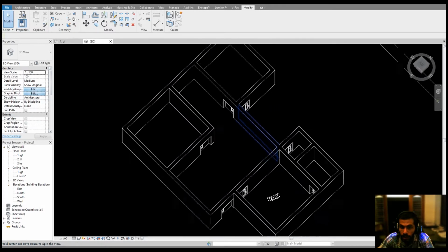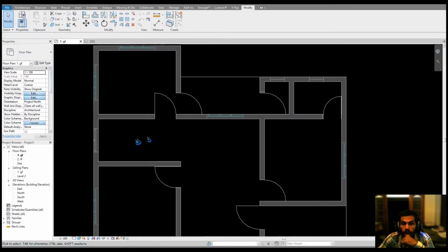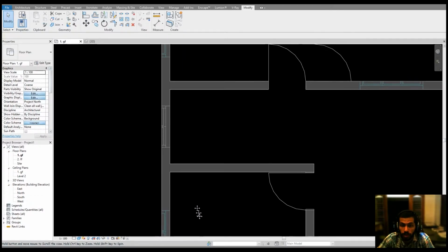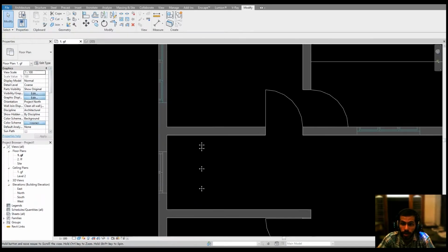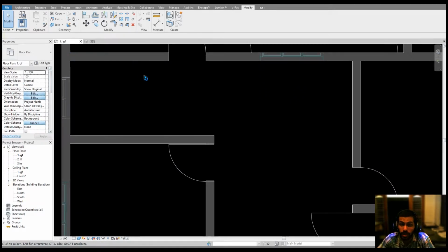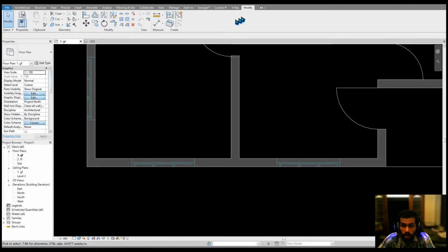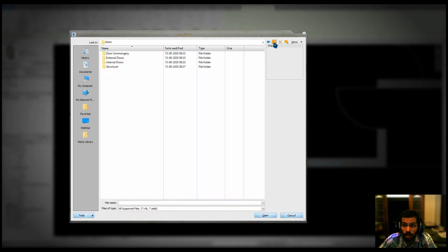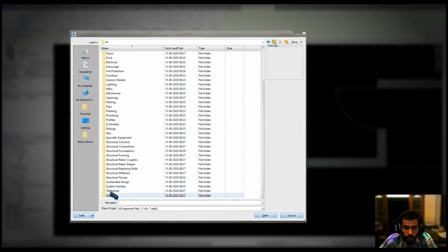Alright, now let's try placing the windows here. There are a couple of 3-panel windows, 2-panel windows, and some ventilators. So first let's try to understand the size of all these things. Get into modify, and you're having a scale right here to measure between two references. Pick 2 points here, and that will show 152.38. So get into window. I'd like to select a 3-panel window right here.